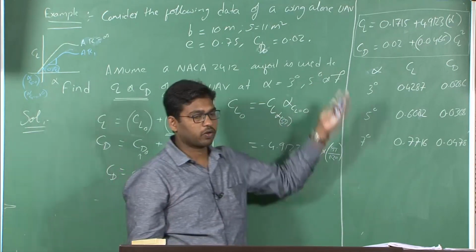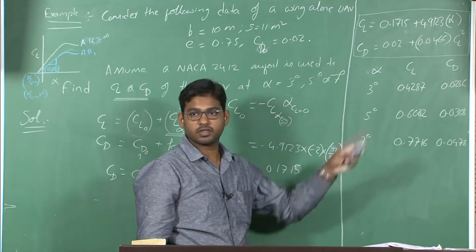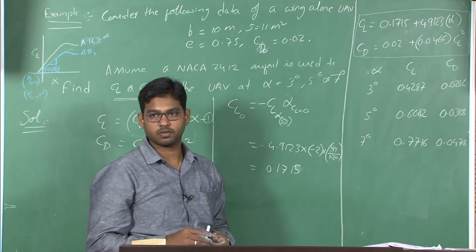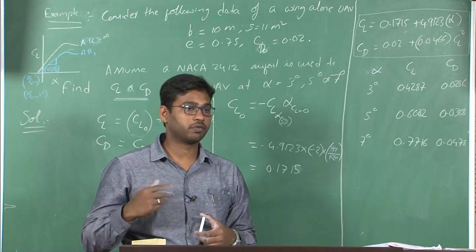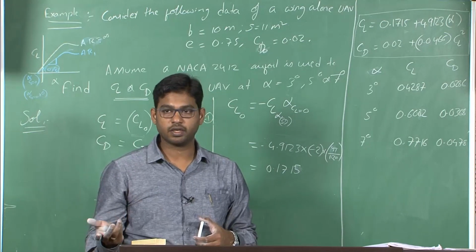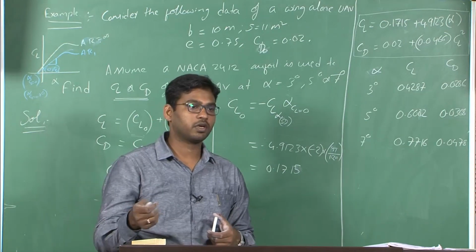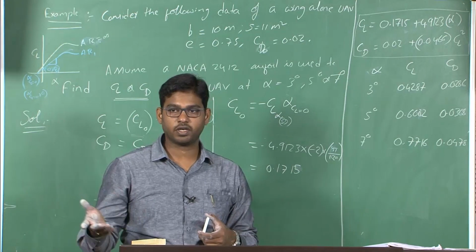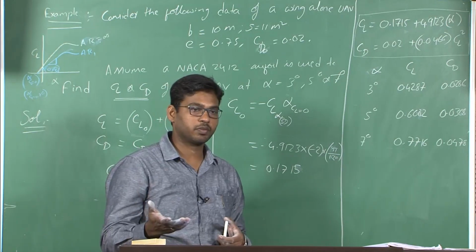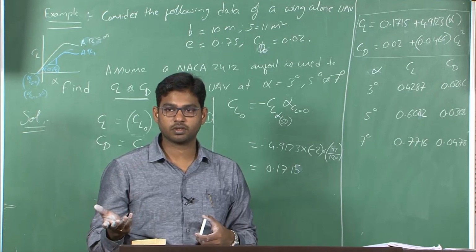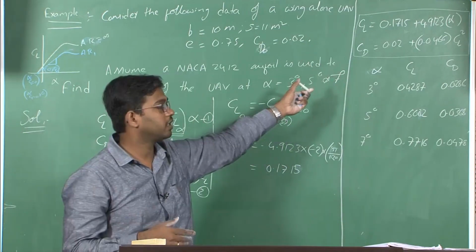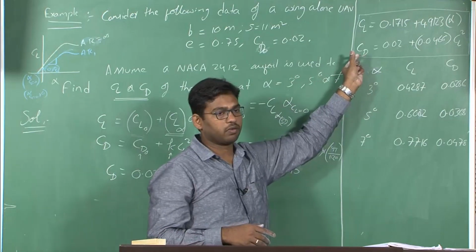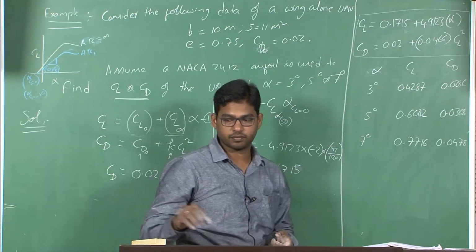Say, which power plant do you need to select? That requires the information of CD, right. During various phases you need to move at different velocities and different flight conditions. So which power plant should be used, and how do you find it? You first gather the information about the requirement of the system. The requirement of the system is drag, so to calculate drag you need to find the corresponding CD.